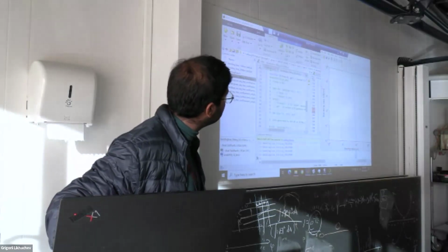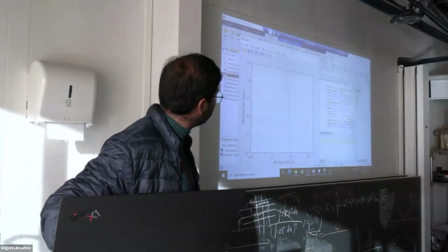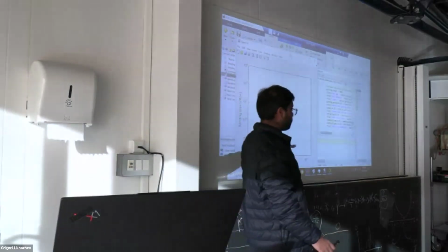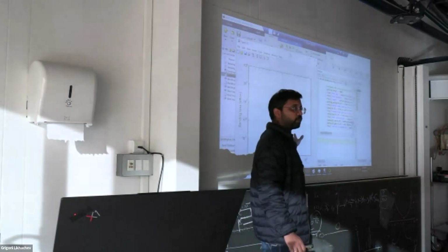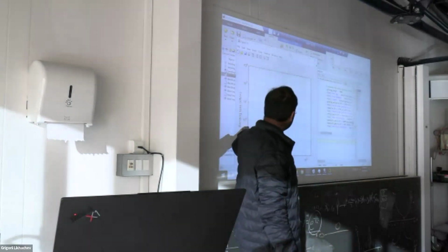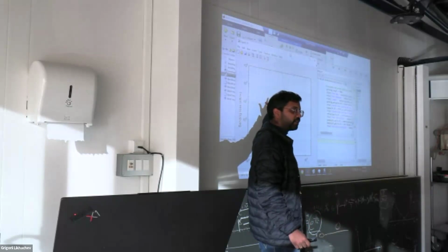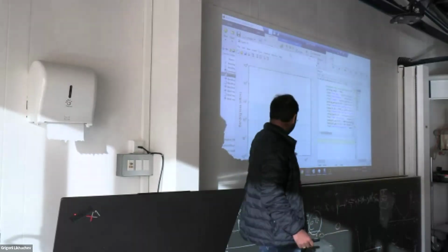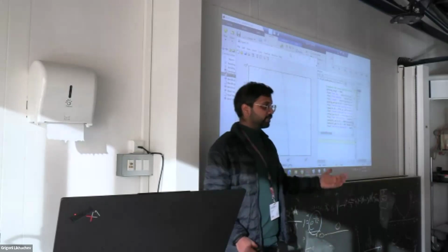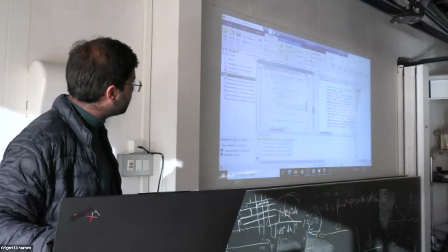Yeah. So this is the log scale I have plotted. This is the bending loss for a 200 nanometer thin platform, where you can see that if you have 10 to the power 0, 1 dB per meter loss, for around 100 micron, you can have that much loss. So if you have that much target, you should not go below this radii. All your radii should be greater than that to have lesser losses. So that's how you can get the bending loss. And I also have the result for 100 nanometer.